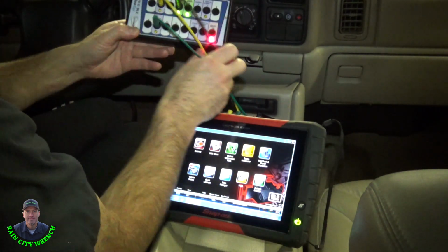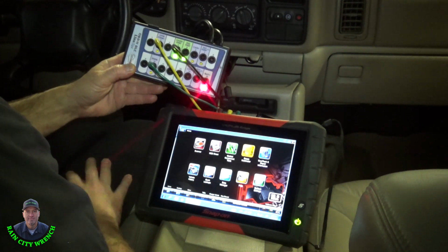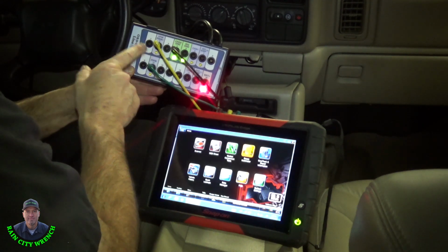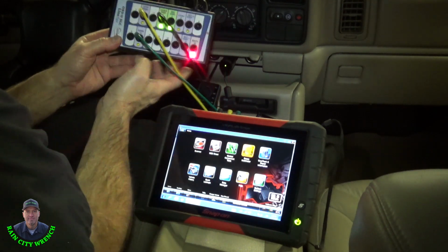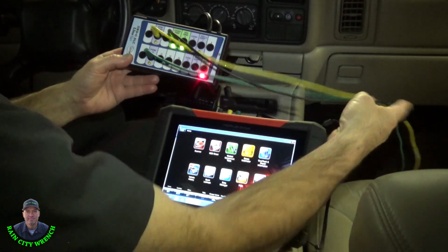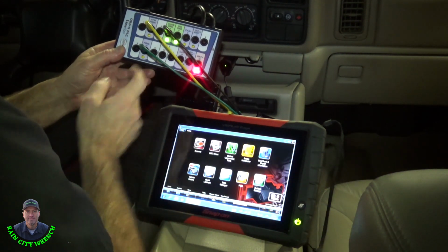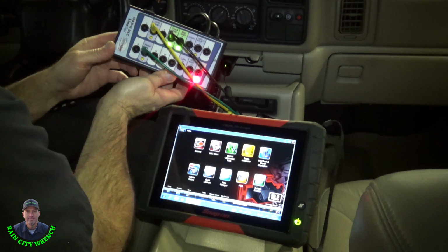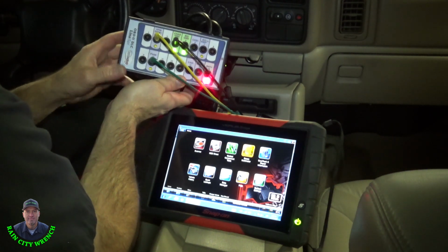The next patterns I'll be analyzing will be inside the vehicle here. I'm going to look at my J1850 communication network. Now this is an '02, so it's really old, and it doesn't have high-speed CAN. High-speed CAN would be on pins 6 and 14. I'm using my breakout box here. It's an AES Wave Line Spy.